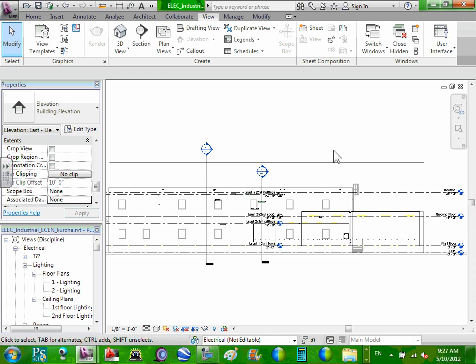Well, that's interesting, because work planes are a different structure. You can make them either act like a floor or act like a ceiling too. And that's probably the biggest difference with a level. A level will always act like a floor. It always sees itself as a floor of a level, not a ceiling, I'm pretty sure.